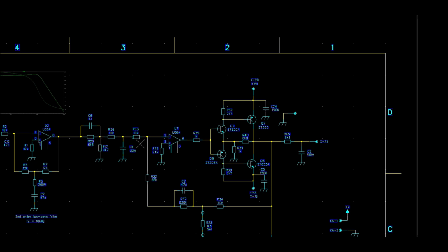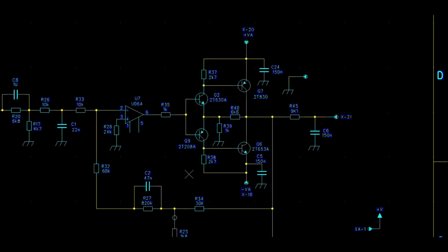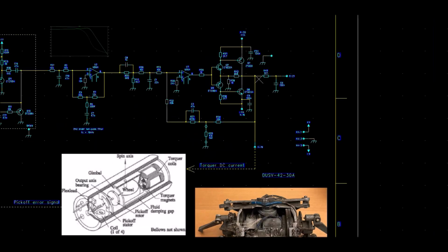The DC voltage is fed to this circuit, which permits probably to have a phase correction. And this voltage here is fed to this amplifier. The gain of the power stage here is defined by these two resistors. Okay, so therefore here we have a gain of approximately 7, and the output is a DC voltage here.